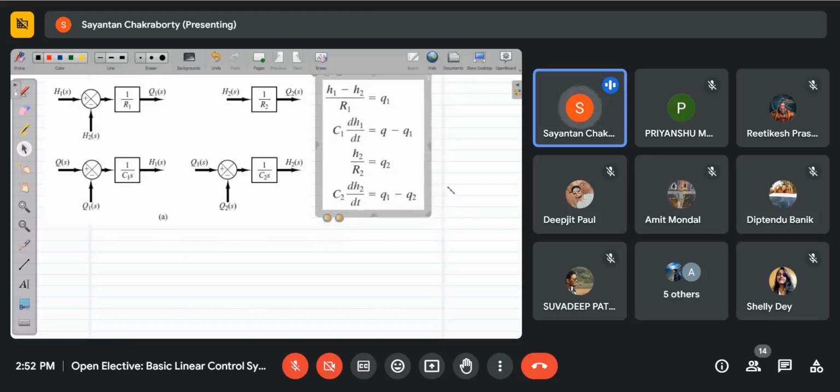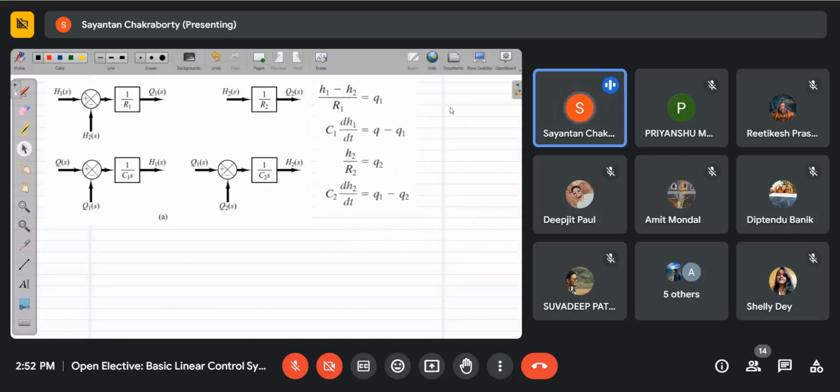These are the four sets of equations which are responsible for these four relationships. See, this relationship in the Laplace domain will be (H1(s) minus H2(s)) by R1 equal to Q1, this one.